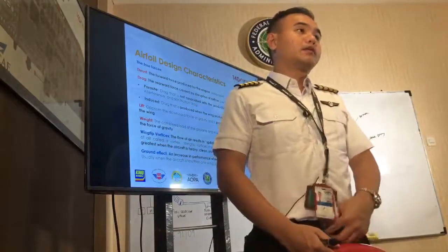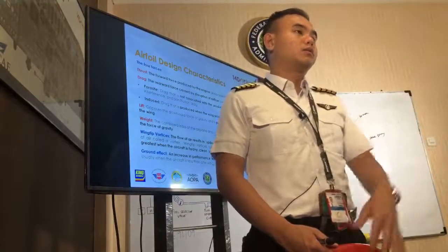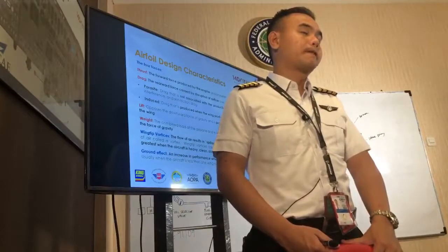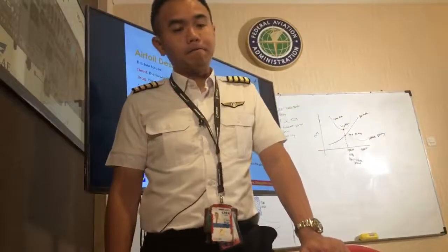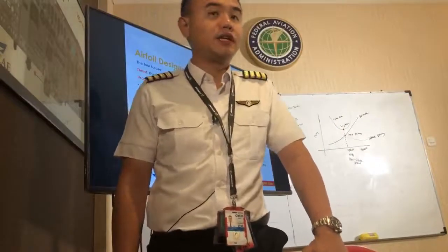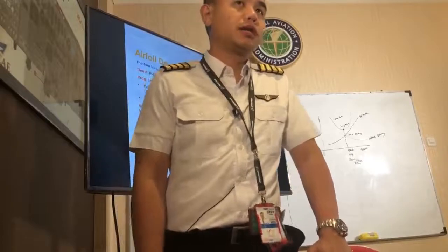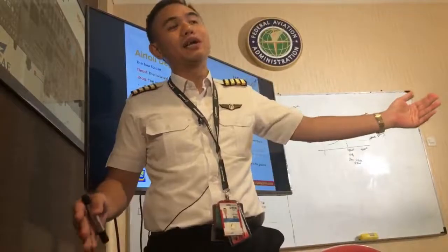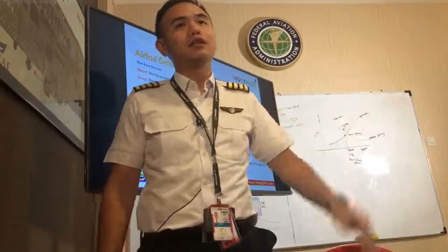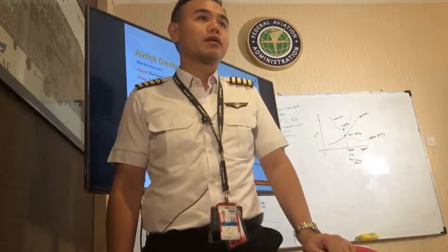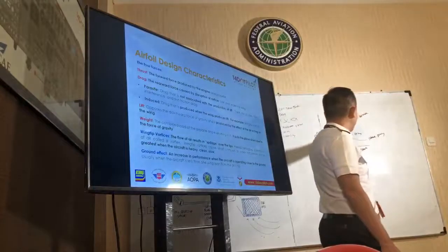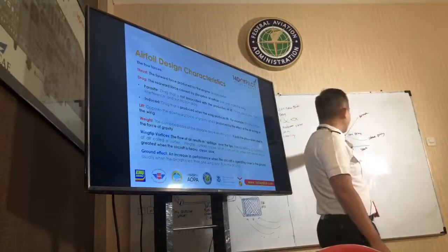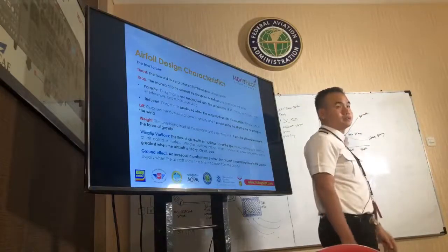What kind of airplane has a 73 knot glide speed? The PA-28, yes, 73. The PA-28 glide, or Vg, is 73. So why do we care about Vg? Because we want to get the highest horizontal distance for every 1,000 feet of altitude lost. Why? Because you have lift to drag ratio at the max, and you're at the minimum drag.